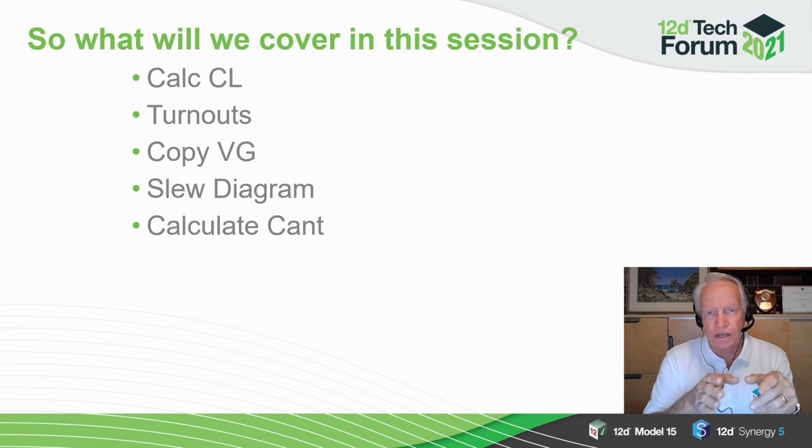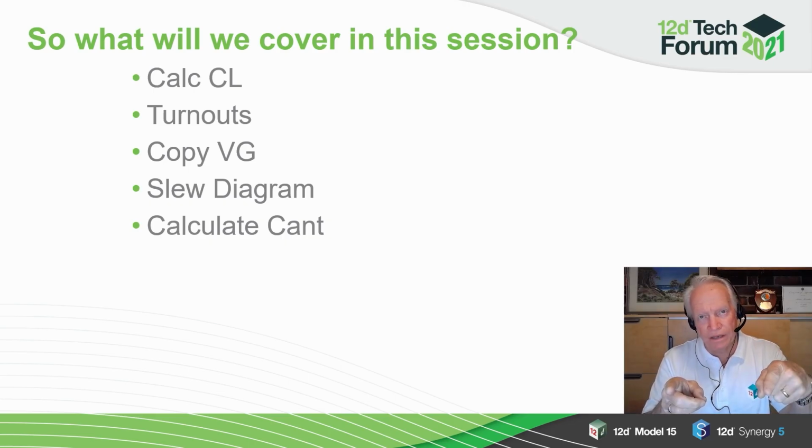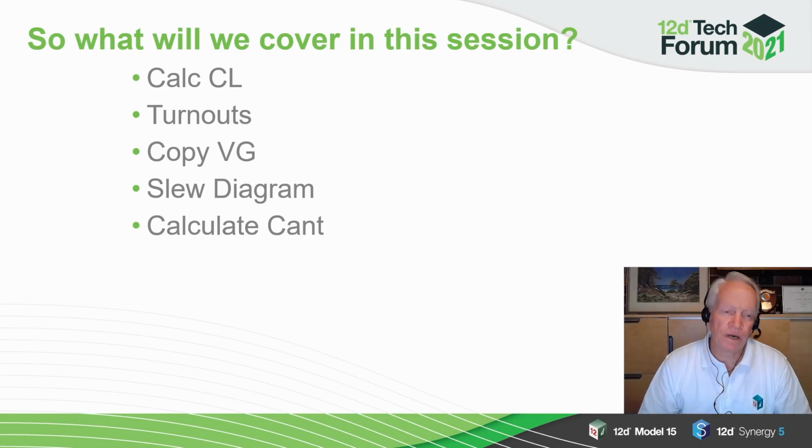Of course, if you're going to the right hand side, then the opposite would happen, where your left track would start to come up through the transition. You would then keep that track high through the curve, back down at the end of the transition, and away you go, level again. So that's what our cant is all about.